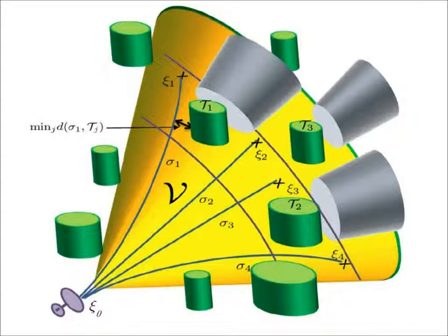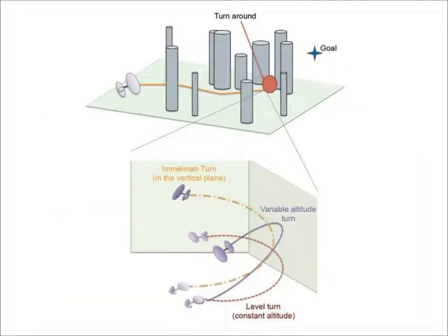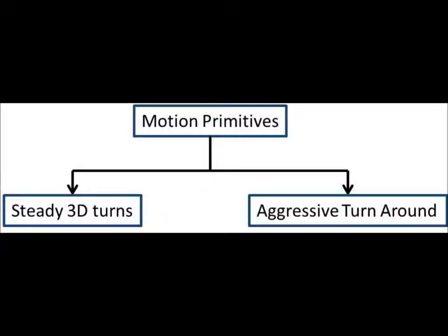First, the algorithms have to identify collision-free paths and the control inputs required to fly them in a very short span of time. Second, the computation of the control inputs has to duly accommodate the nonlinear dynamics which govern the motion of an airplane. In addition, the motion planner should be equipped with maneuvers which can allow the aircraft to backtrack from dense, impenetrable pockets of obstacles. The two families of motion primitives introduced in the paper are continuously parameterized in the space of control inputs.